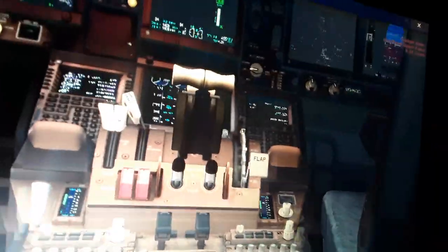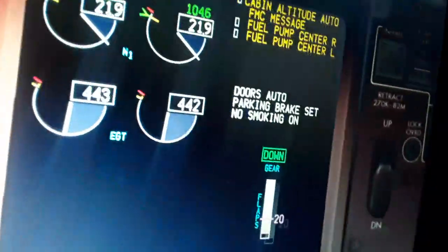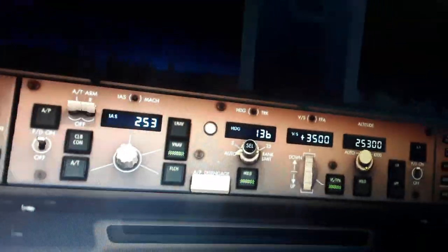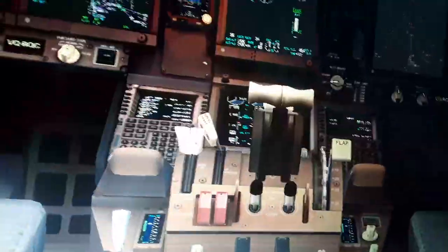So you can see here we have these switches for disconnecting the hydraulics for maintenance on the ground. We have the circuit breakers panel. We're gonna set here the flaps 15 degrees for takeoff. You can see the flap set, the position here in the display. We have also the autopilot display, one more view, nicer view. And hold on, I'm gonna show you now the ADIRU, the air data inertial reference unit.